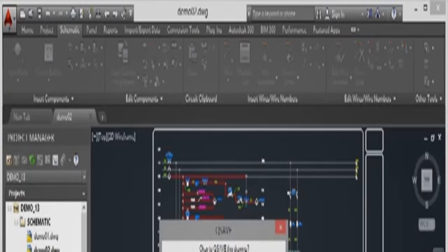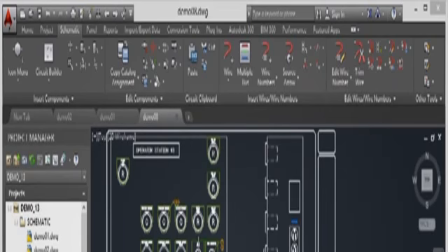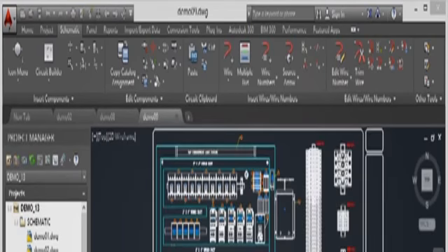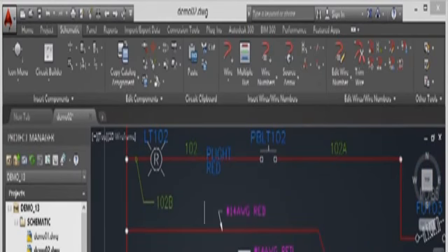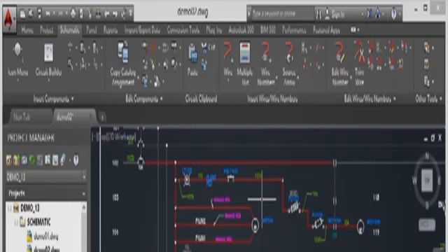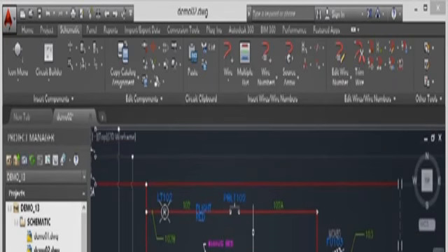I'm going to OK that. It saves this particular drawing, so it OKs it. And what you'll notice now is it goes into the other drawings as well that have those parent-child links. So it's going through the 2 panel drawings because there's components on drawing demo 02 that link back to those panels. So it's done a complete retag now. If I zoom in on this area here, anything that might have numbered up here is now renumbered on the panel drawings as well. That's a retag per drawing, and obviously it's picked up the parent and child relationships.